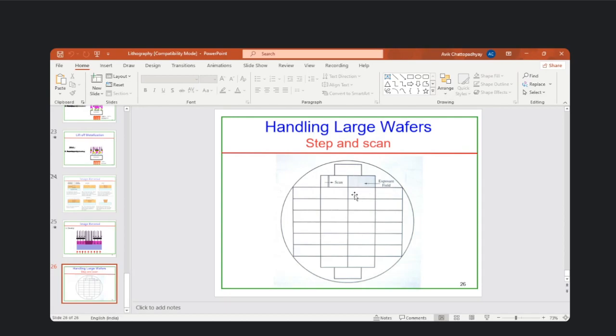It is not possible that you say okay, I will replace one die. It is not possible. Okay, because the whole thing is done in one go, almost one run, or people call it batch processing. The wafers are basically processed in batch processing. These are such small dimensions, you cannot do anything with that. And even within the die, if one transistor fails, one component fails, the whole die you have to throw. So,